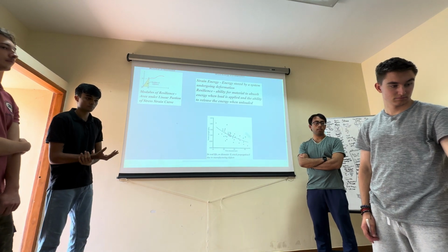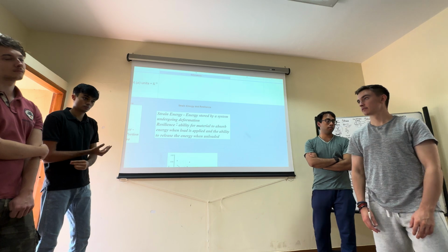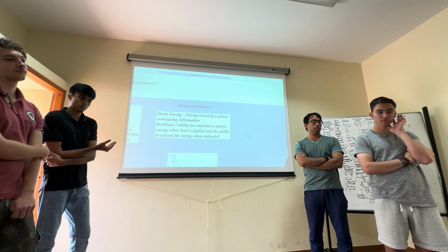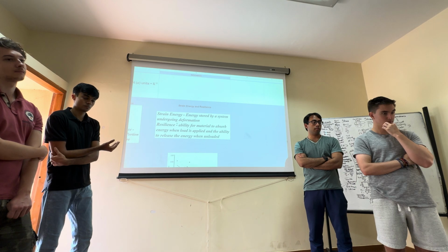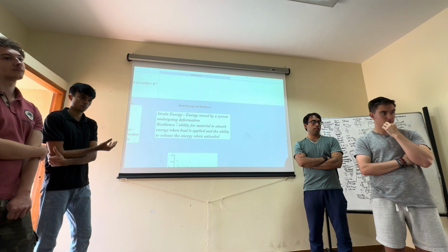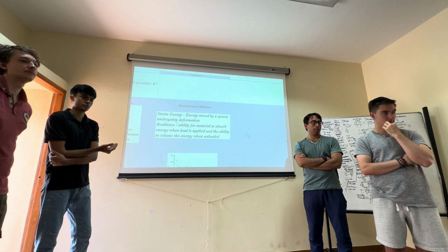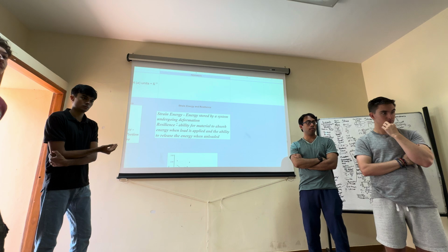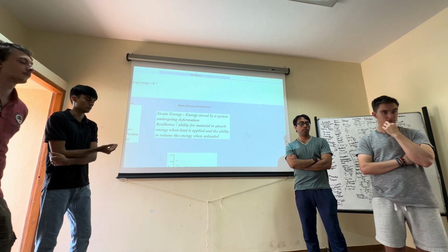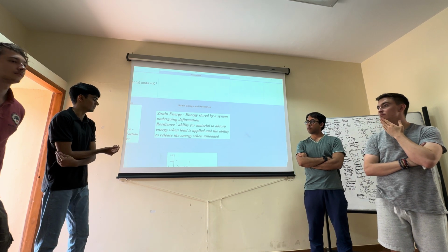So this is under the assumption that the proportionality limit and the yield point are the same. They need not be. In terms of the linear limit and the elastic limit, in some materials they could be different from each other. So all the way up to the elastic limit, even though part of the curve is non-linear, you will still be able to get back, and you have the resilience over there. I think in my research, I just used this. Yeah, I understand what you're saying.